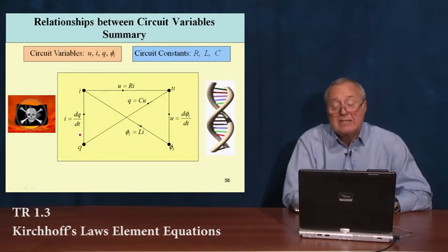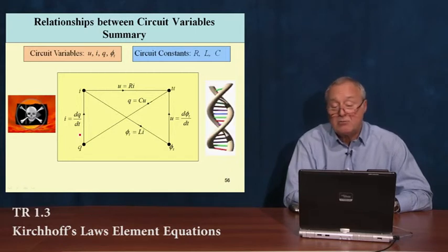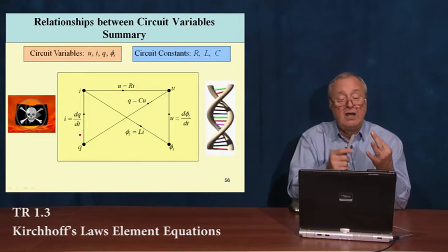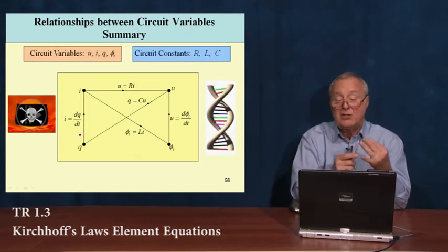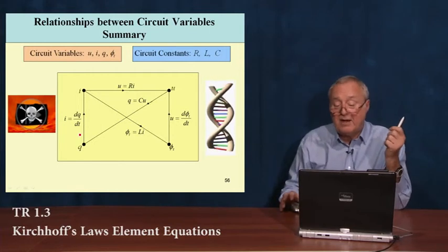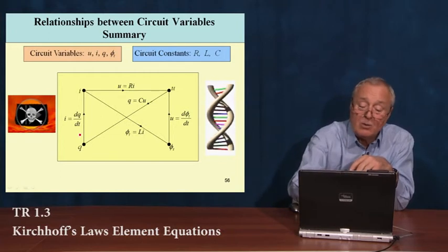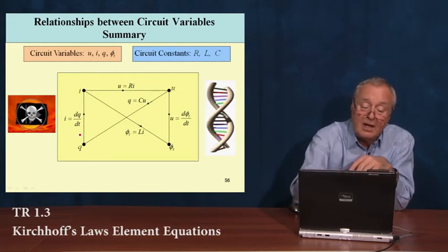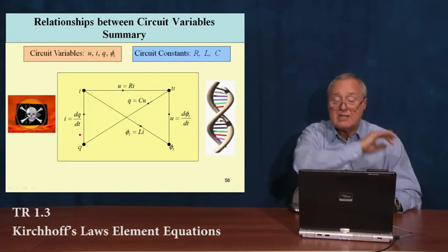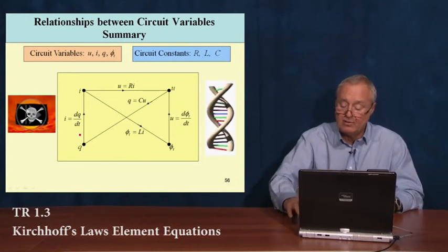And now the last slide, summary. On this graph you have these relationships in time domain between 4 circuit variables: voltage, current, flux, total flux, and charge, and they are related, each pair except Q and phi(t), by these equations that you have on this slide. So that way we have discussed, it is a memristor which is the missing element relating charge and total flux, but I'm not going to discuss the memristor.